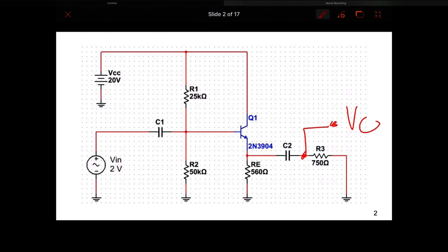Let's continue on. So, all right, we have the common collector. Notice that there's no collector resistor. Everything else is your standard voltage divider. C1 is your input capacitor. C2 is your output capacitor, and there's no emitter bypass. So write that down, and then we'll continue on.